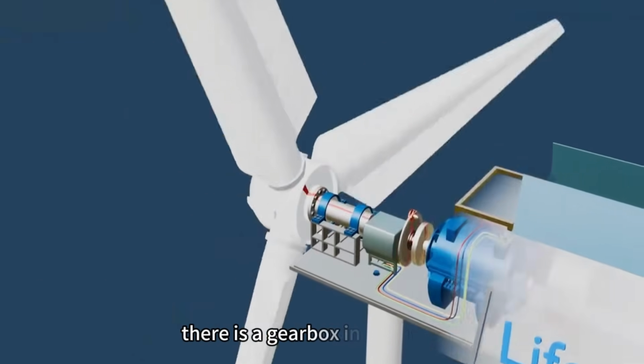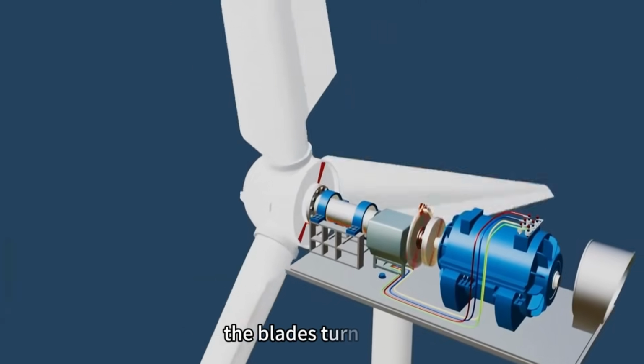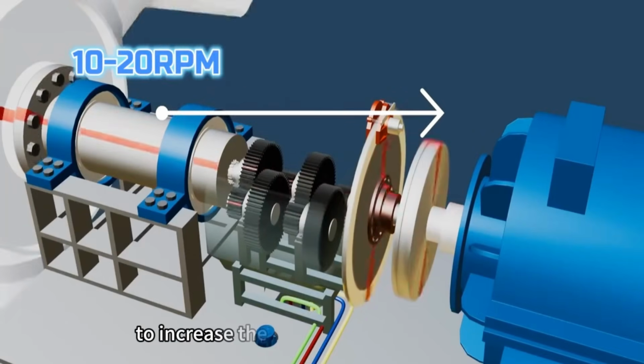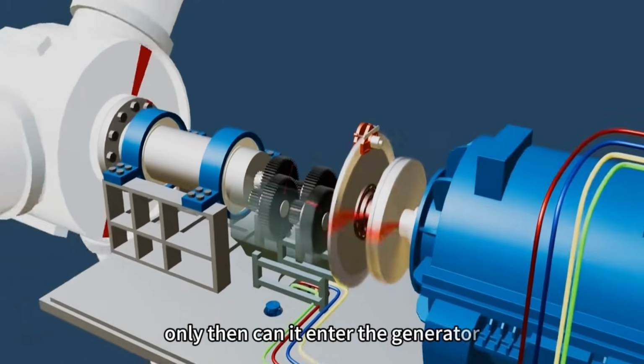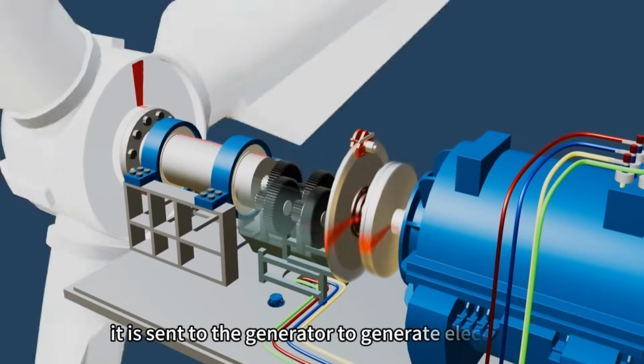There is a gearbox in the nacelle, with a transmission ratio of 1 to 90. The blades turn slowly. The speed is amplified through multiple gears to increase the speed to 1000 to 1500 RPM. Only then is it in the generator's normal working speed range. Then it is sent to the generator to generate electricity.